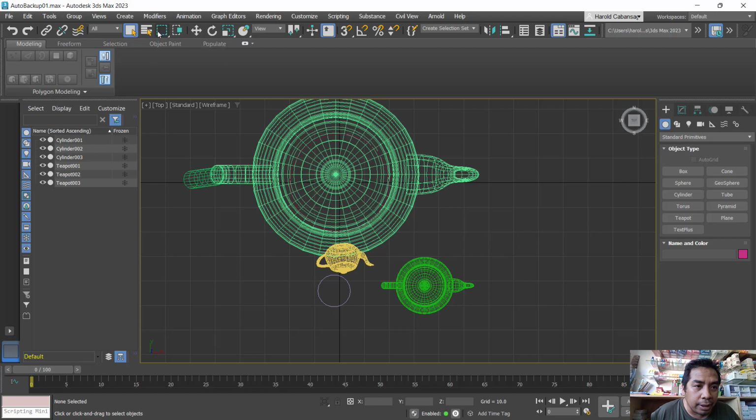And then if I would like to add, I will just press Control. As you can see, the cursor adds a plus sign onto the selection, so it becomes additive. If I press Alt, there's a negative sign onto it, so that means it becomes subtractive selection mode.